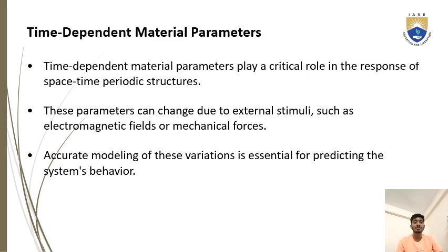Modeling time-dependent material parameters. Linear models describe the time-dependent behavior of materials using linear differential equations. Non-linear models describe the time-dependent behavior of materials using non-linear differential equations. Prony series, a mathematical representation of the relaxation modulus. Generalized Maxwell model, a model that represents the time-dependent behavior of materials using a series of spring-dashpot elements. Applications of time-dependent material parameters.